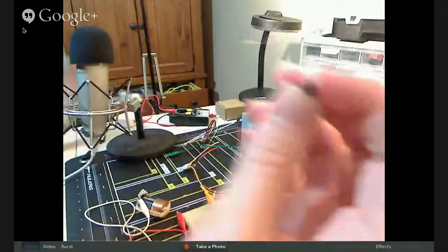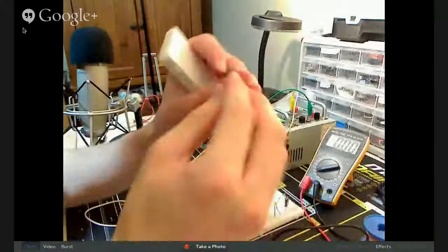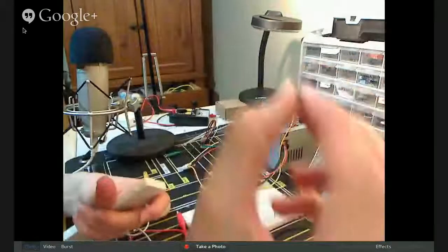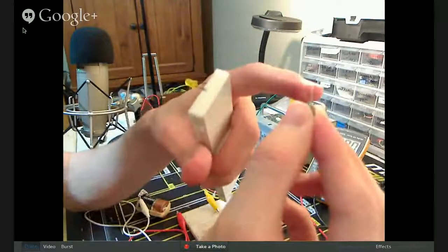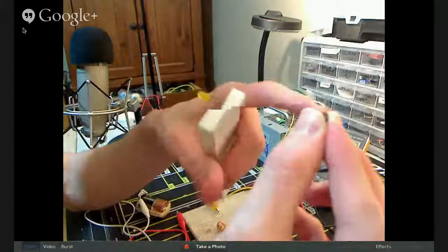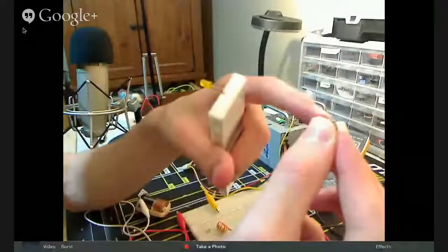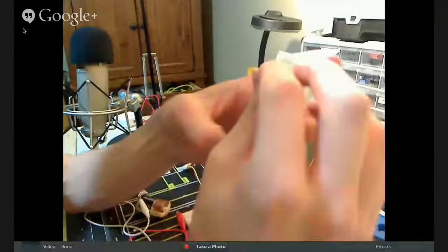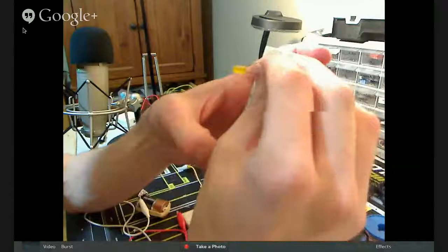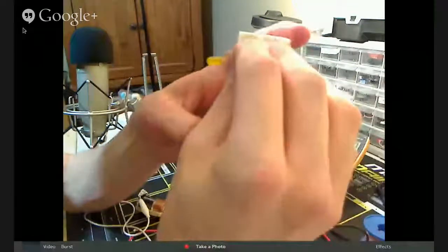If you put the flat side to your right, then the leads are emitter at the top, base in the middle, and collector at the bottom. Or the opposite: collector at the top and emitter at the bottom, so that our breadboard matches our schematic pretty closely. We'll go ahead and put that into our slots here.